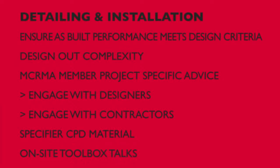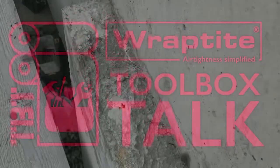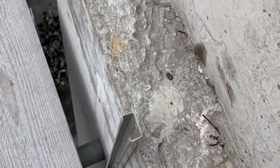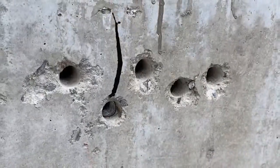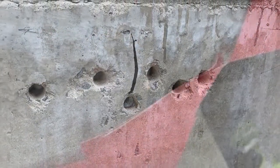While systems like our WrapTight and WrapTight UV membranes go a long way to make the installation as straightforward as possible, there are still a few important considerations around preparations of substrates and site handling to bear in mind. Some of these, for example, ensuring the substrate is free of sharp or uneven protrusions or lapping runs of membrane to shed water outwards, apply equally to self-adhered and mechanically fixed membranes alike.